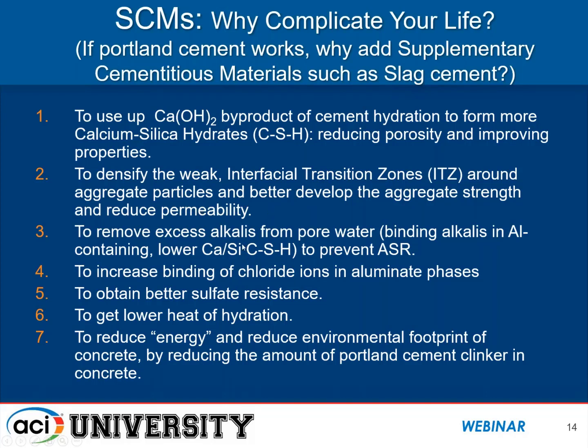Many SCMs will also reduce the alkalis that are in the pore water. The pore water in concrete is typically pH 13 to 14. And it will bind up some of those alkalis in the calcium silicate hydrates and help prevent alkali-silica reaction. It will also increase binding of chloride ions that are in the water, penetrating through, so they become bound and they don't make it to the reinforcing steel to cause corrosion.